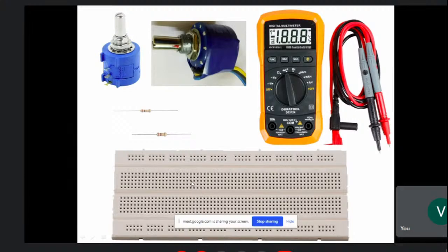After the breadboard came, it is very easy to connect the circuit. The breadboard is connected in such a way that there are two strips, and 5 points in the middle, and every 5 points are connected vertically, and the horizontal two strips upside and downside also have points connected.